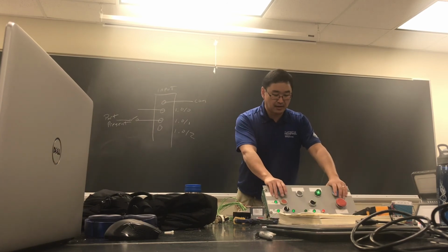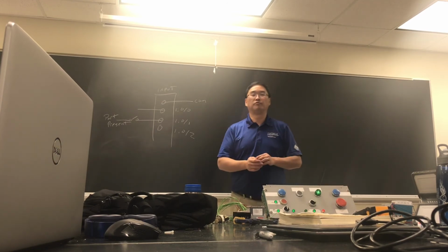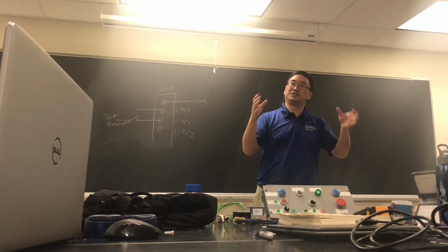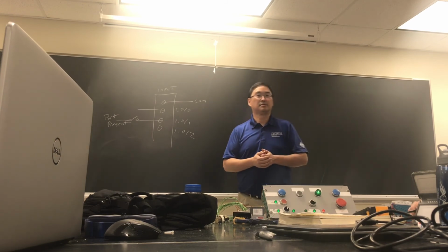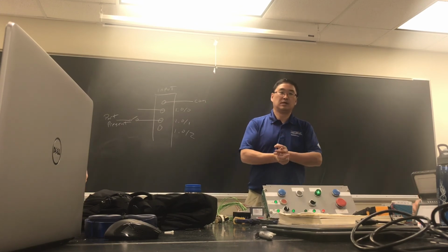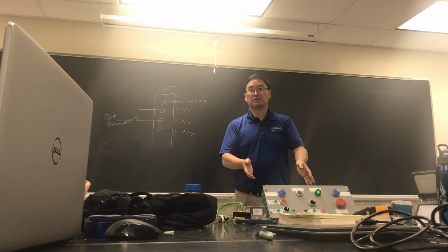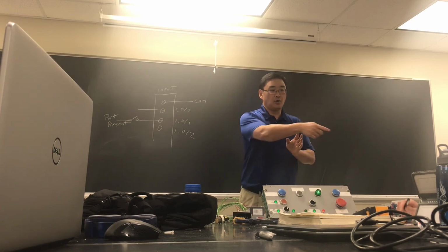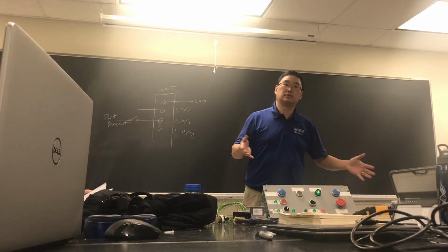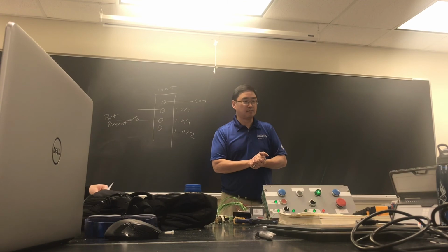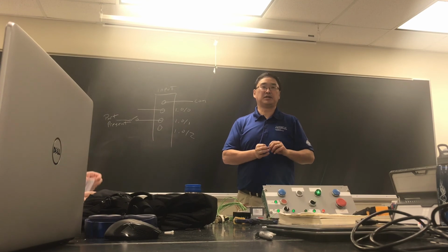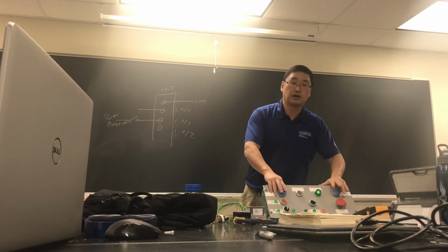For the panel itself, just go into PowerPoint or Visio or something and just draw a representation of it. I'm not concerned about the exact size and dimensions and all that. All right? Get your logic working first. You've got the I/O listings already anyway, so it's not like you have to go and map those. You just have to draw it up, really. But I would program it to your individual PLCs for testing, and then when you think you have it, you can come over and try to physically do it.